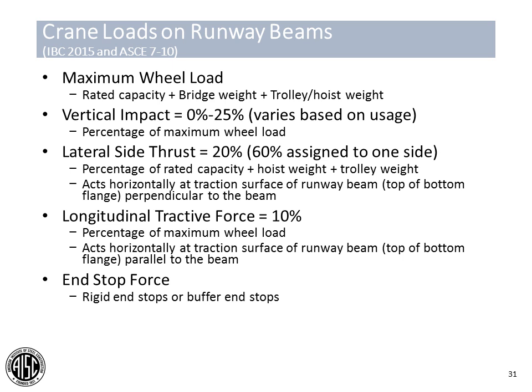One other item that needs to be considered is the end stop force. This is either the hoist and trolley assembly hitting an end stop on the end of the bridge girder, or the end trucks hitting an end stop on the end of your runway member itself. There's a couple of different end stops that can be specified.